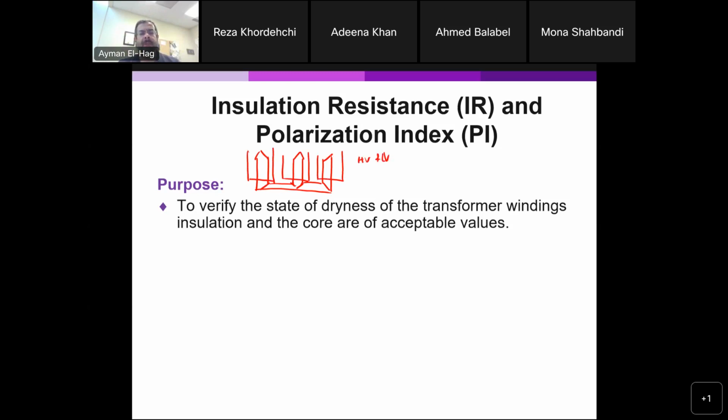Then you close the top part of the transformer by adding the final magnetic material. So this is one winding, this is another winding, and this is the third winding, and you have the core material completely; this is a 3-leg transformer. When you energize the transformer, you have the flux going through this. We call all of this the active part.